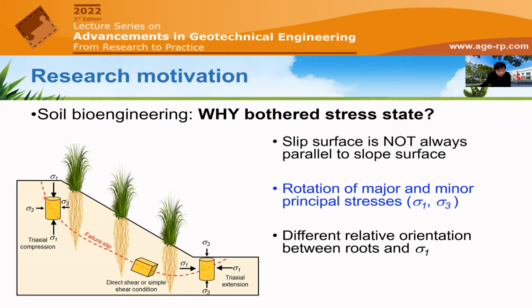However, if you look at other positions of that slip, close to the crest, you may have a triaxial compression-like stress condition. But if you look at the toe, there will be some kind of triaxial extension stress state in the soil sample.